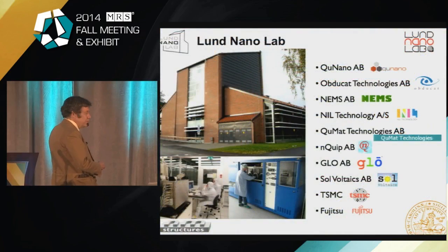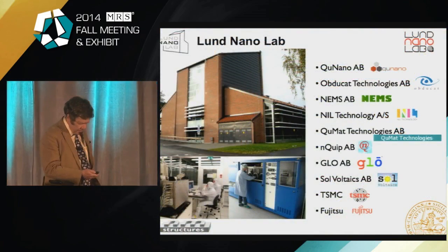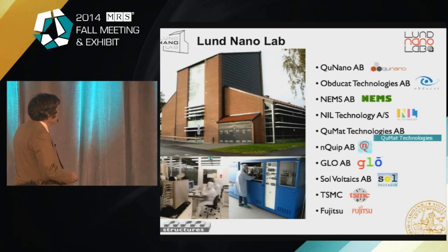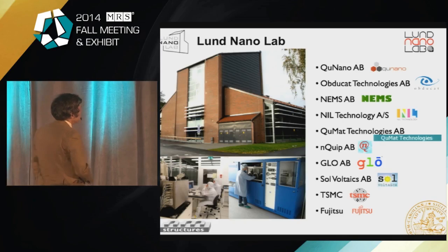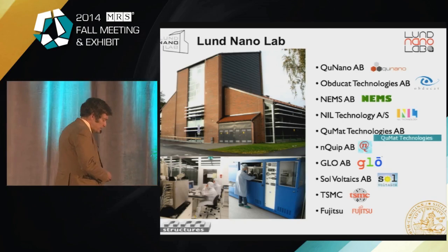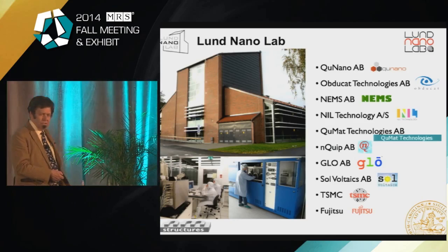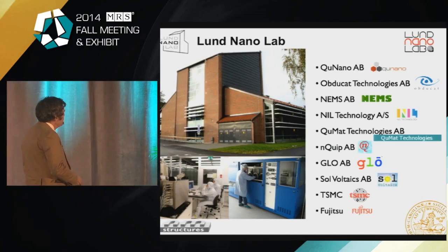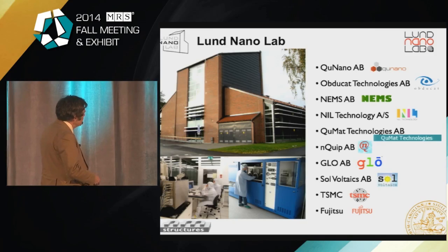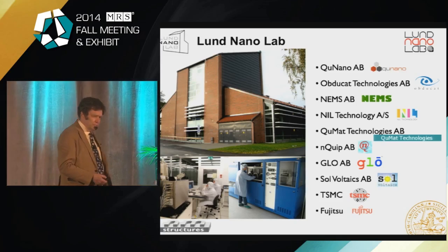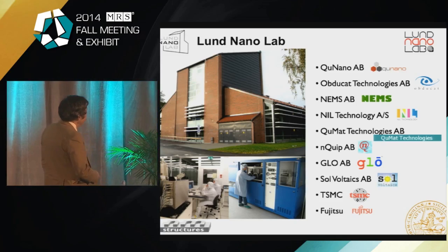We have a much smaller lab already. We have had it for almost 10 years, Lund Nano Lab, which is a dedicated lab for nanoscience for the Nanometer Structure Consortium, extremely well equipped for crystal growth. We now have 5 MOCVD systems and 1 chemical beam epitaxy system. We have many advanced clean rooms with all kinds of patterning techniques like e-beam, focused ion beams, nano-imprint lithography, and deep UV.